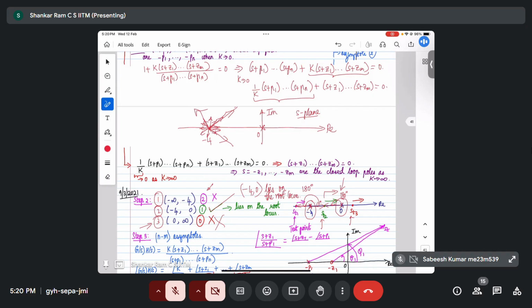No, in fact, when we plot the root locus, we are going to have complex conjugate roots, right? See, what is the point here? You remember the denominator polynomial of T of s: a naught s to the power n plus a1 s to the power n minus 1, all the way till an minus 1 s plus an, right? In our physical system, whenever we get the transfer function of a system, we are going to deal with polynomials with real coefficients.